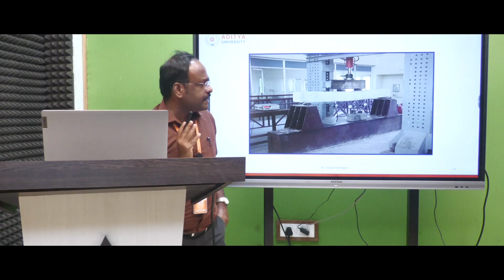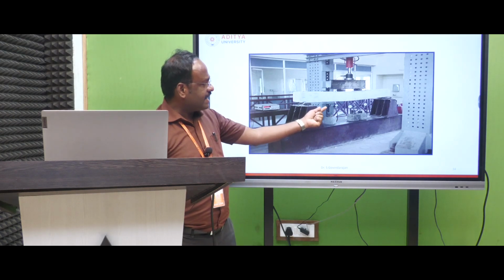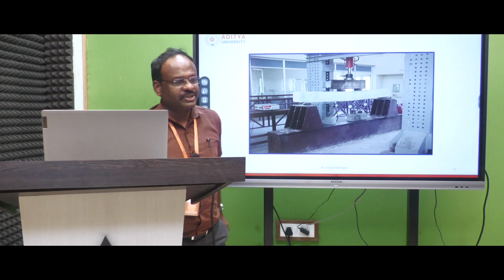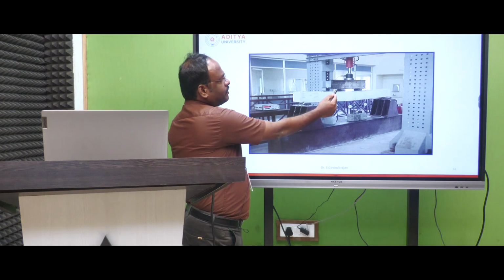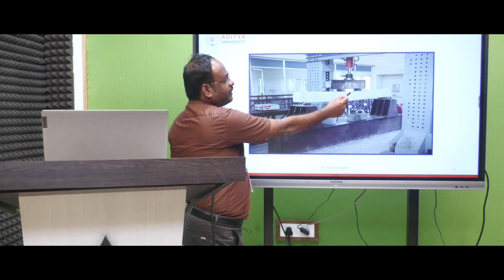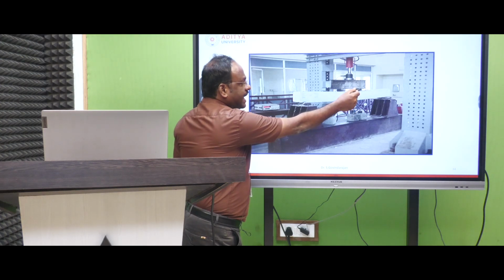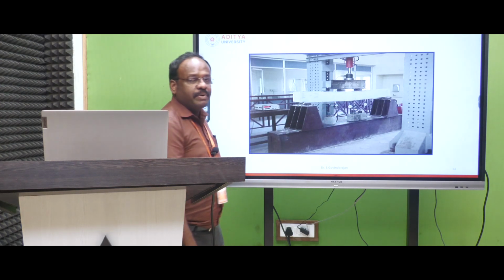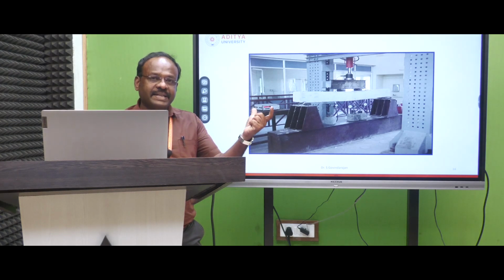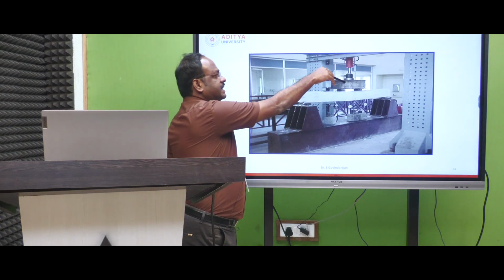Here I place dial gauges at three places. Using the dial gauge you find the deformation: one is at one roller, another at the center where the maximum deformation is taken, and another at the right side below the roller. Then you find the deformation value at the three places, and the load acts at the center.